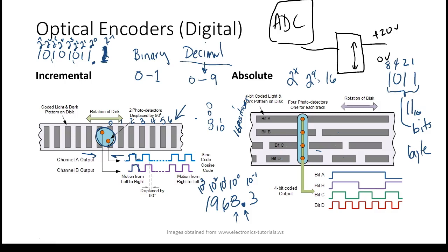On an absolute encoder, it would be the number of bands. So if I've got a certain amount of distance and all I've got is 16 positions, that is it. Let's say the band is this long right here and I've got only 16 positions. That means every position would be 1/16 of that space. So if I want a long absolute sensor with better resolution, then I have to put in more bands. For every band I put in, I have to have another sensor.